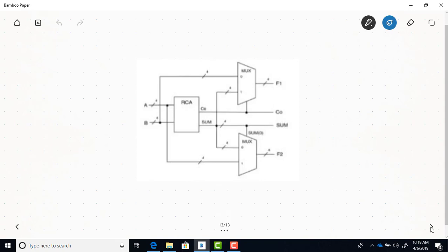This is a 2-to-1 mux. Okay, we've got 2 inputs and a single output, and since we only are choosing from 2 inputs, our select line is just a single bit, because if that single bit is a 0, it's going to allow the data on the D0 input through to the output, and if that select bit is a 1, it will allow the data on the D1 input through to the output.